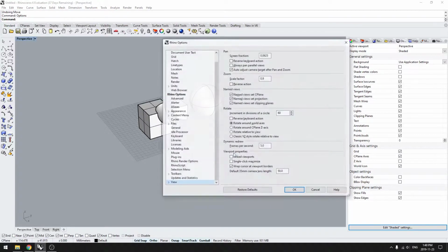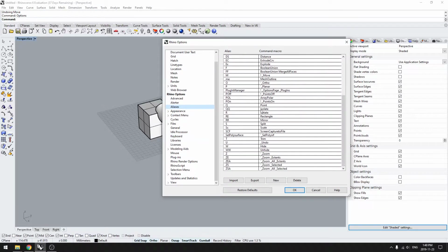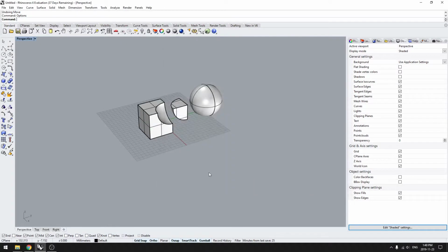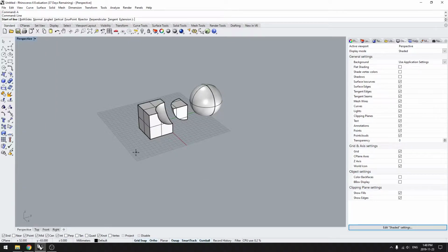Another variant of that is the apostrophe. We're going to find an apostrophe command like zoom. You see it like apostrophe zoom. How that works is that it doesn't kill your previous command. In fact, it puts it on hold or pauses it. So if I were, once again, drawing a line, I click the start of my line, and now I have to choose the end.